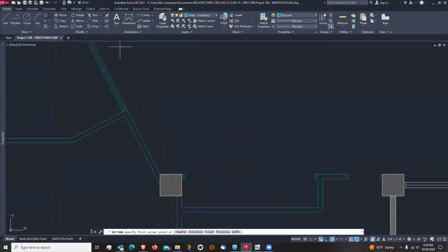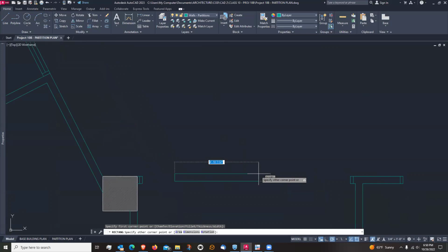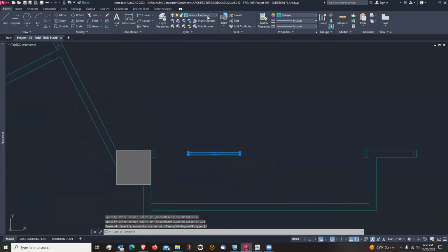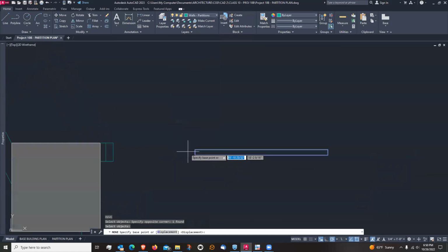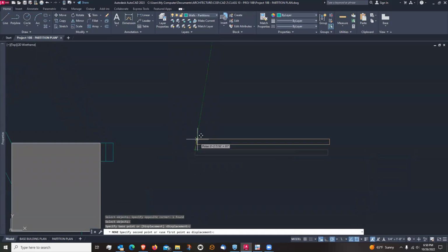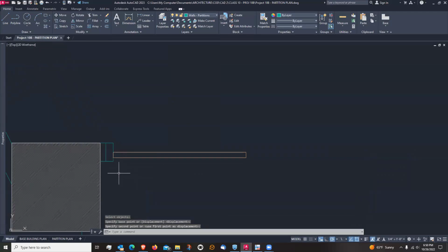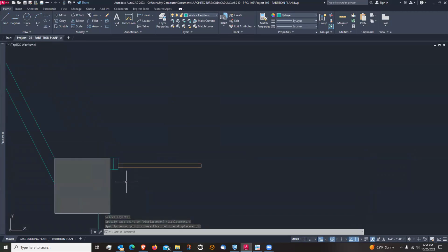So I'm just going to use my buddy, the rectangle tool here, and I'm going to make a door that is 3 feet long. So 3 feet, and then instead of hitting enter, I will hit tab. And the thickness of that door is, as I said, 1.5 inches. And while I'm at it, I'm going to just put it right on the doors layer. All right, so let me just move it into place. So all I got to do is pick a corner and align that corner with the midpoint of the door, or the door frame, excuse me. So there's my first door leaf.